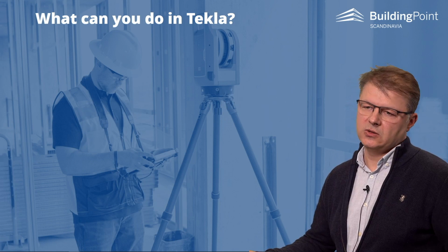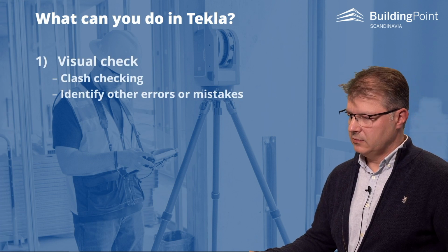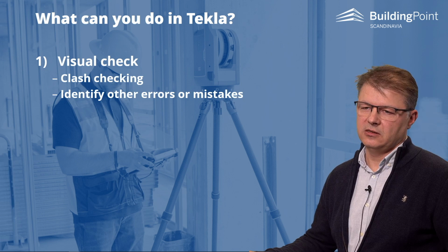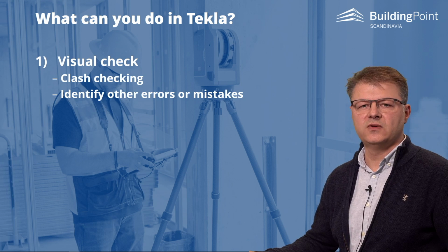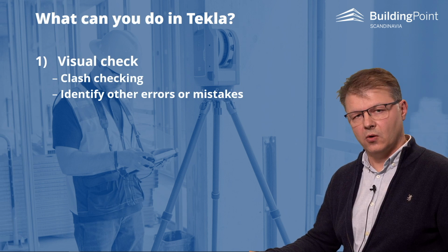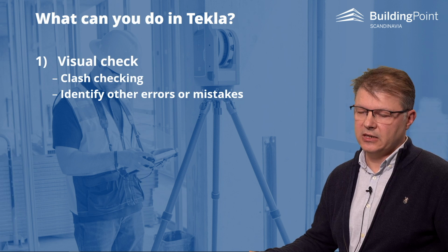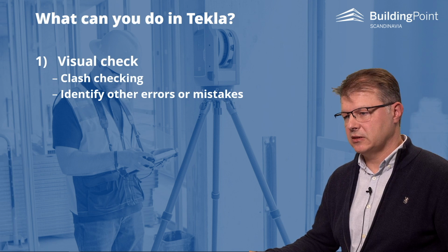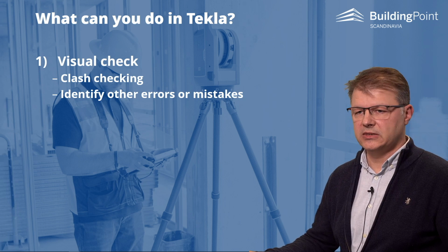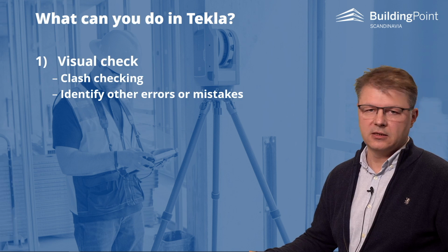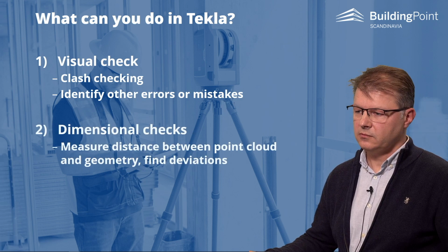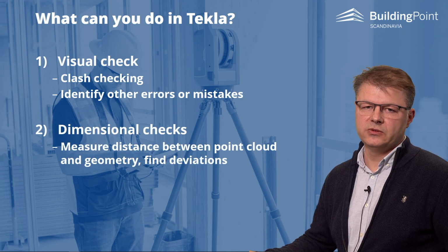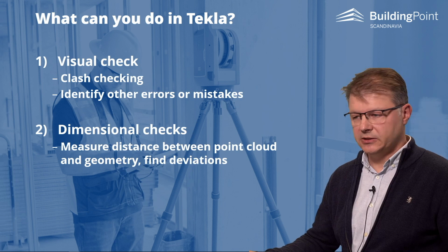What can you do with the point cloud in Tekla? Of course a lot, but to begin with, you're going to do the visual check for the whole thing. If it's correct or not, you can see that some elements are not mounted or placed incorrectly, a general overview. You can do the dimensional checking, like for the detail check.